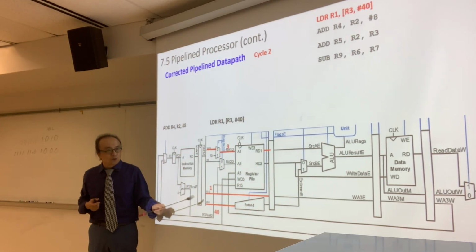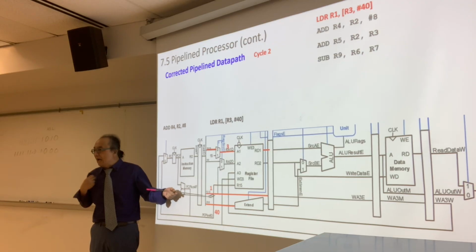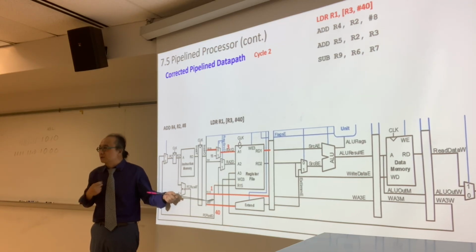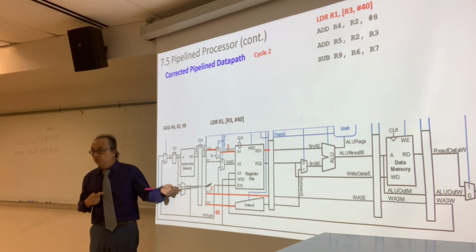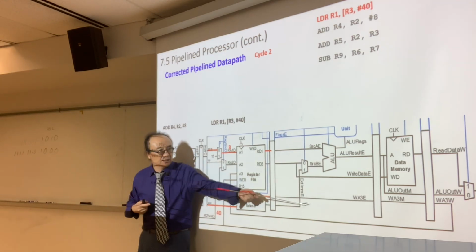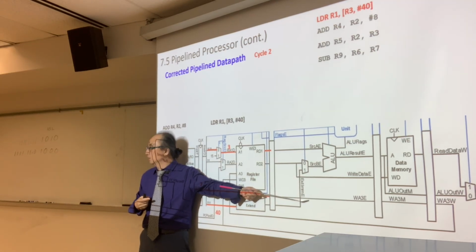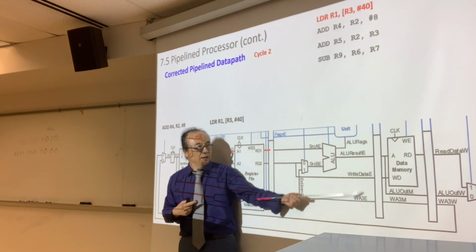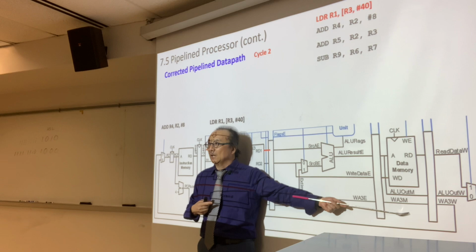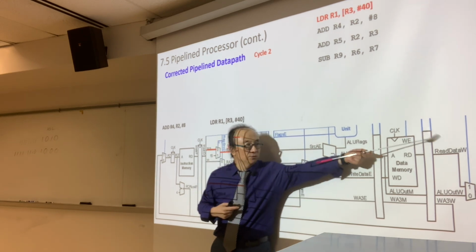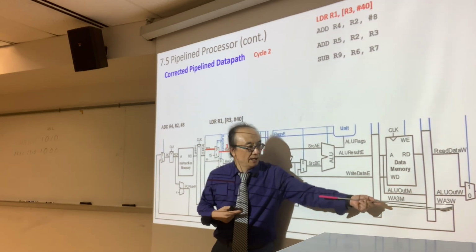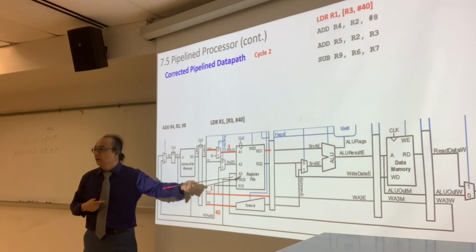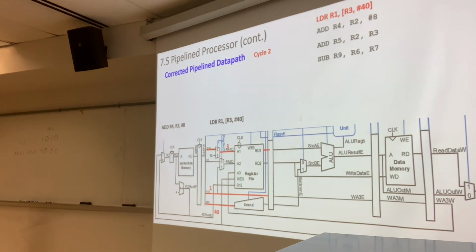So in order to maintain my RD, I don't want to forget about this RD. We're going to pass this 1 into the next stage when you get into the execution stage. And then I'm also going to carry that 1 into the memory stage. And finally, when I get into the write back stage, I'm going to have 1, put it back here, and write into the register. Let's move on to the next diagram. The first page is the second diagram.